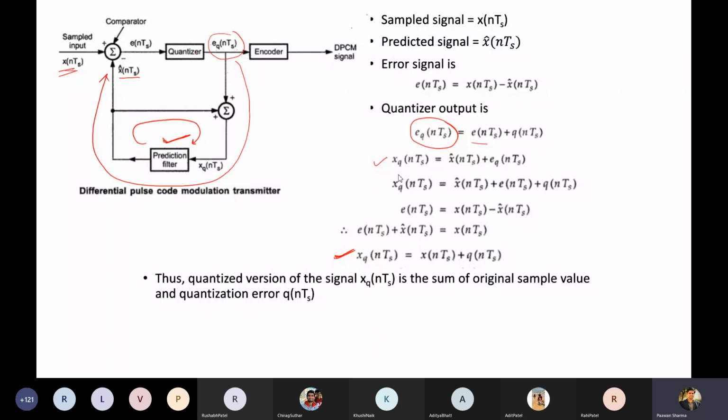The increment or decrement is definitely by a certain amount with reference to the past value. So we are trying to leverage that correlation. We are trying to use this much increment has taken place, this much has decreased. So we are using this difference in the samples as an error signal, and then we are transmitting that signal.